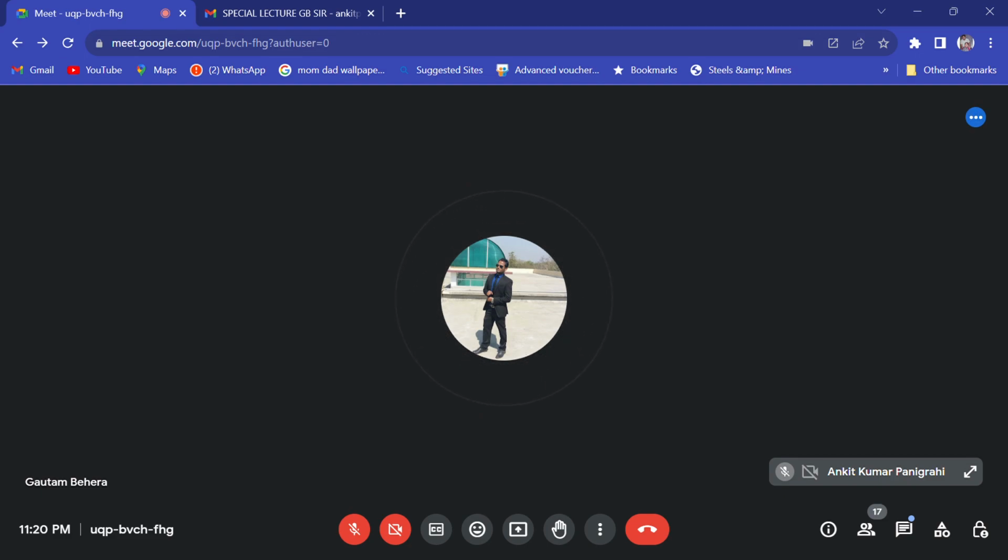The concept is, to make stainless steel, you need a large amount of stainless steel scraps, right? You also need some amount of mild steel scraps to add iron, and you also need some amount of nickel. You add high carbon ferrochrome, which is the source of chromium. Nickel is the source of nickel. Stainless steel scraps will give you both nickel and chromium, and some iron. And mild steel scrap will give you some amount of iron, right? The point is,